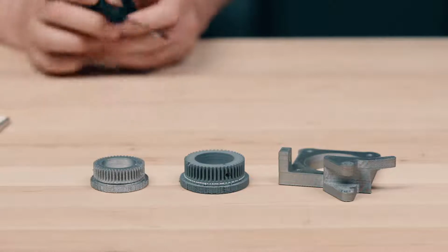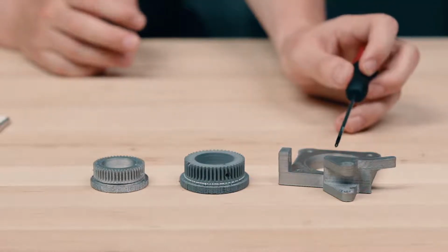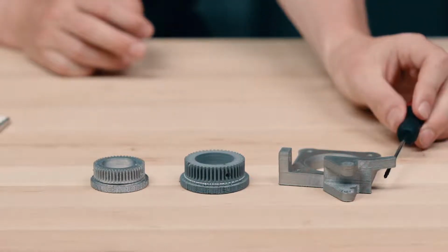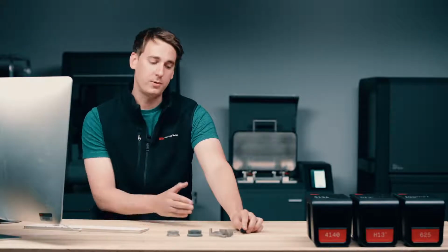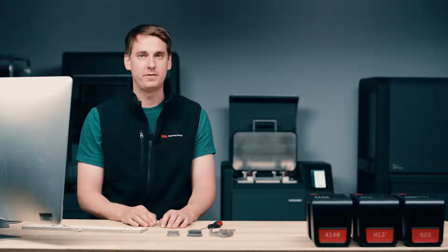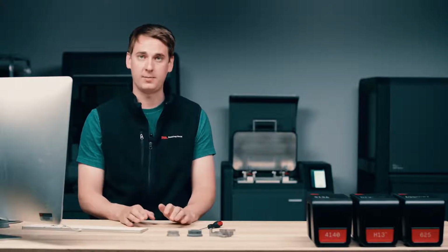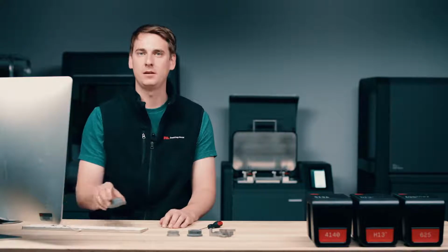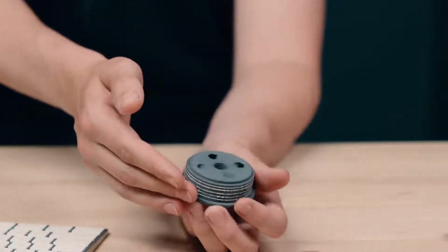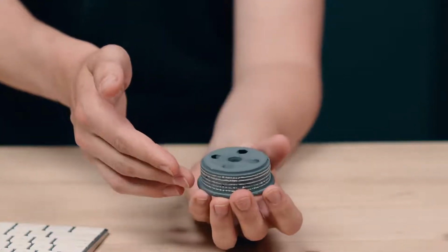But what about a more complex part, like this motor mount? This part would definitely require supports due to these overhangs. Without supports, gravity would take over and the part would collapse. It's important to note that Fabricate is going to analyze each individual part and generate a custom support structure for that part. These supports are very smart. They do much more than just ensure your part doesn't collapse. For example, strategic seaming. This ensures that your supports are always easily removed and you never have any mold locking occur.